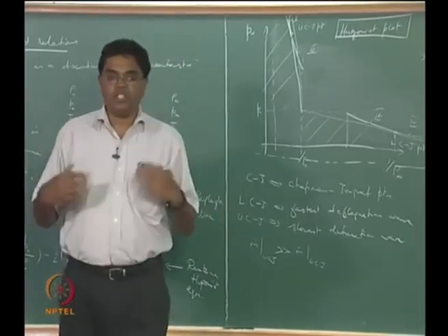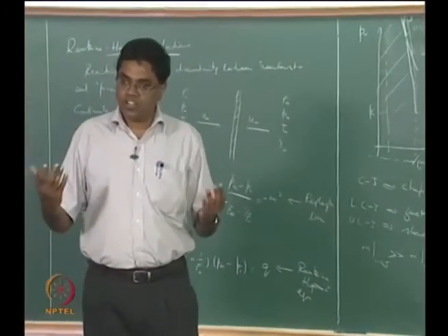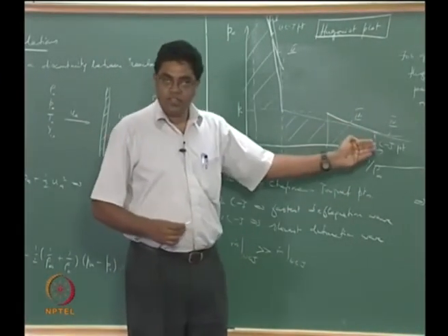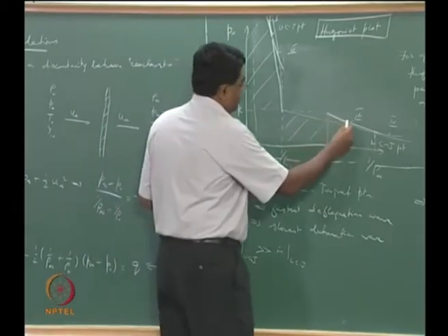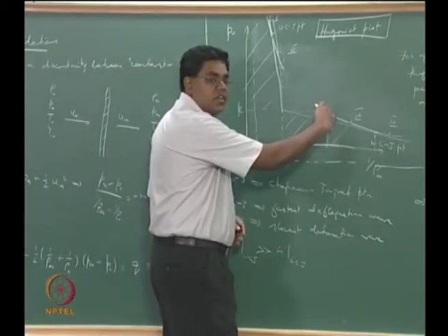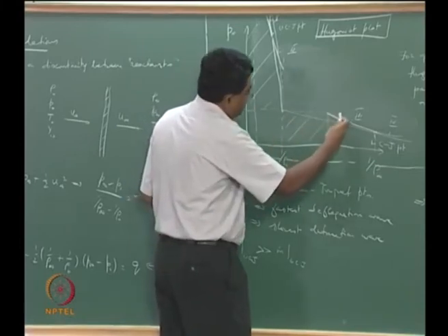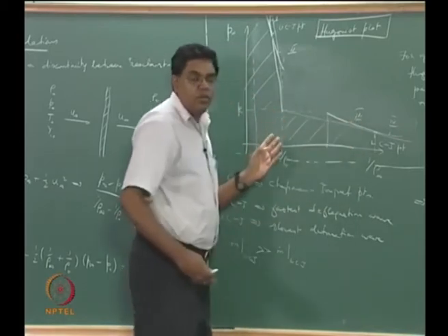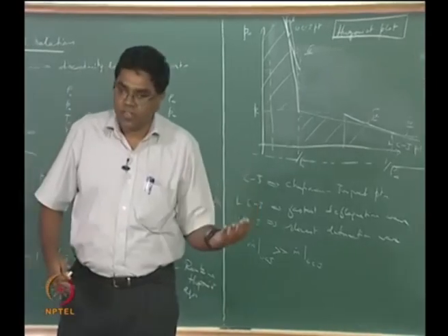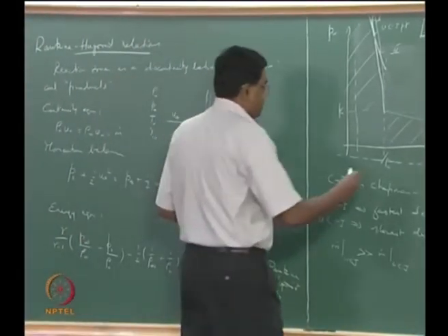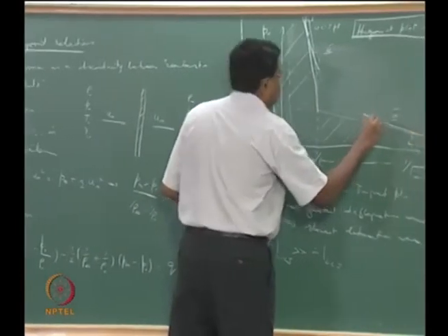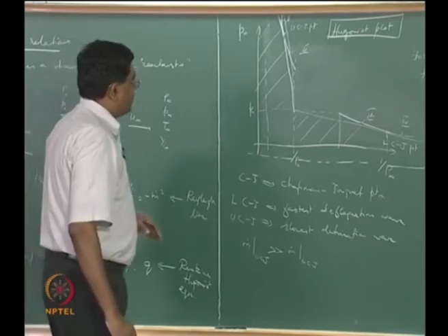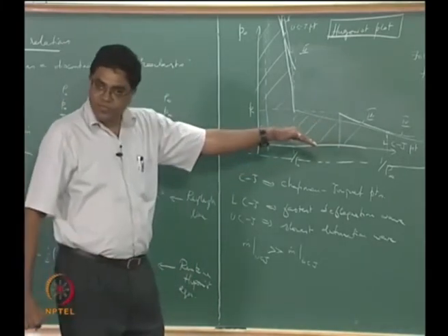Similarly, if you now begin to look at this side, what it means is in a deflagration we are looking for an expansion. So when you're now looking for an expansion, that means the pressure should decrease and the density should also decrease. If you now look at this region, the pressure decreases not a lot and the density decrease, or I should say 1 over rho infinity increase, is also modest. Therefore a rho infinity decrease is also modest, right. So you are not having a fairly large decrease in P infinity and rho infinity, and therefore you are expecting a weak deflagration.